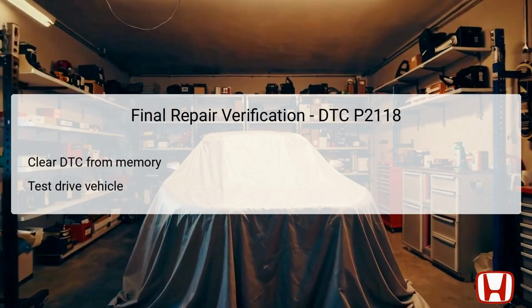After completing all necessary repairs, it is vital to perform a final verification to ensure the issue has been resolved. Start by accessing the onboard diagnostic system and clearing the DTC P2118 from the system's memory. Following this, take the vehicle for a test drive under various conditions to replicate situations that may have previously triggered the code. Monitor vehicle performance, particularly the responsiveness of the throttle and engine behavior.